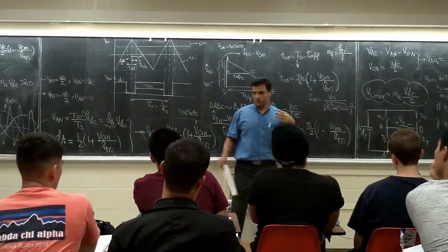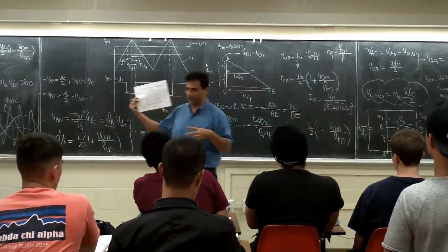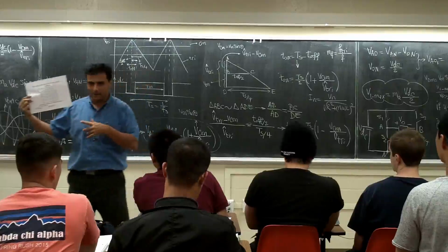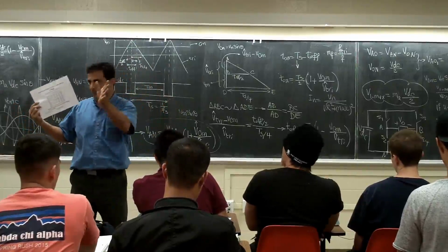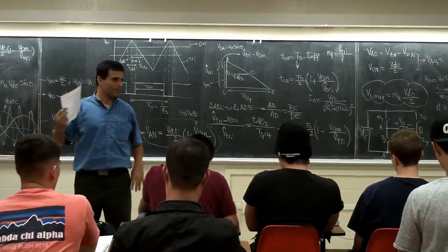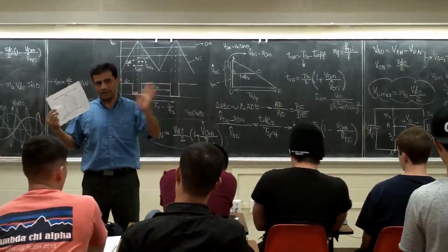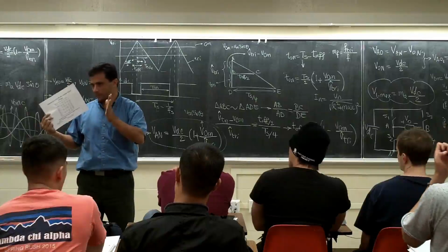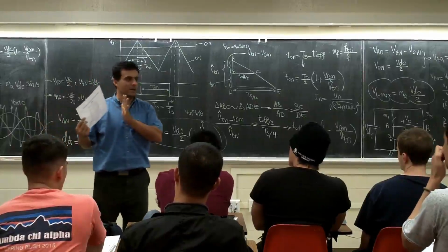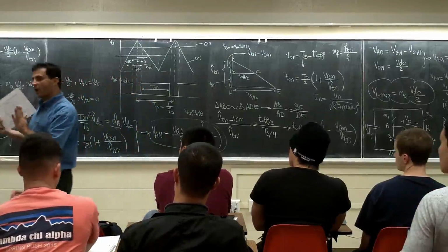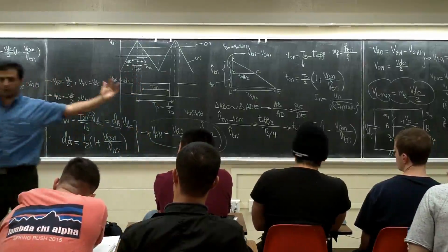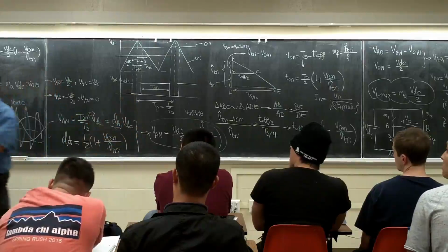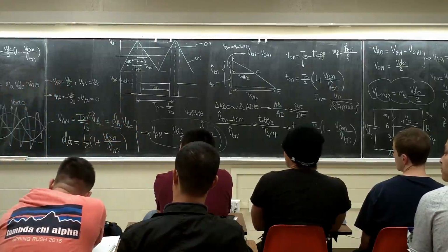Better THD. So you can see here, with this technique, opposite of what we had before, where we had just a square wave, or a half bridge or full bridge, and harmonic elimination, we can eliminate a few of them. This one, if you select a very high MF, the first harmonics are here, and the next one is going to happen all the way over here.